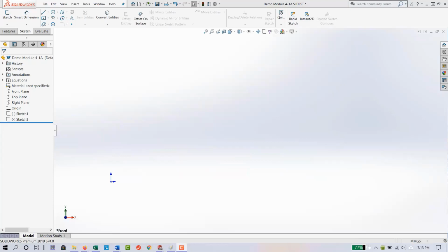The next thing we need to check for is the visibility settings. To do this, we go to the Heads Up toolbar and notice the eyeball icon. That's the one we'll be working with. It has a light background. You can change that to a dark background. However, what this does is it locks all of the options in the drop down, and then we can't change them. So you want to make sure that that has a light background by clicking in the area beside the eyeball.